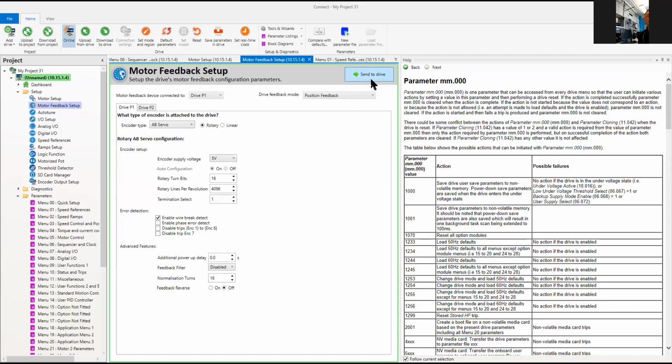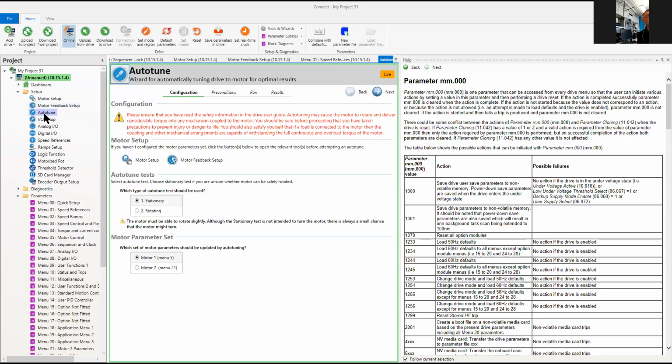I move back that feedback reverse, go to PID parameters, because now it is feedback. Now go to loop control. A loop control is supposed to have some PID parameters set. We have to go for tuning to get some parameters.